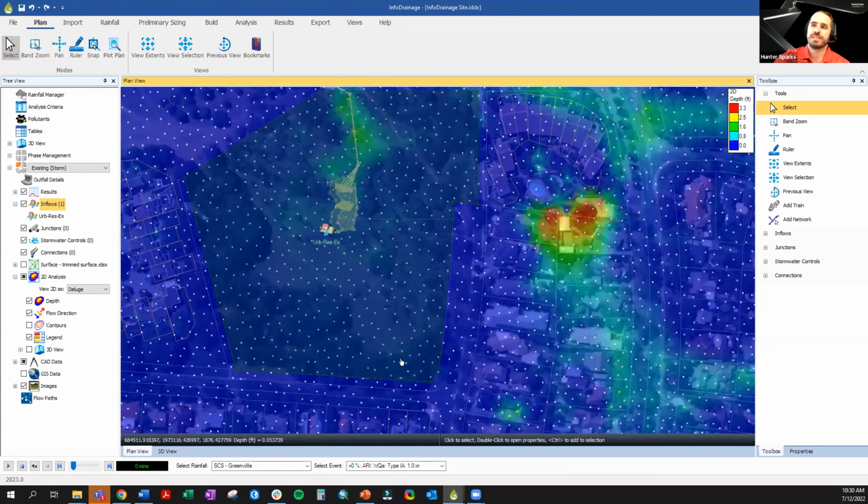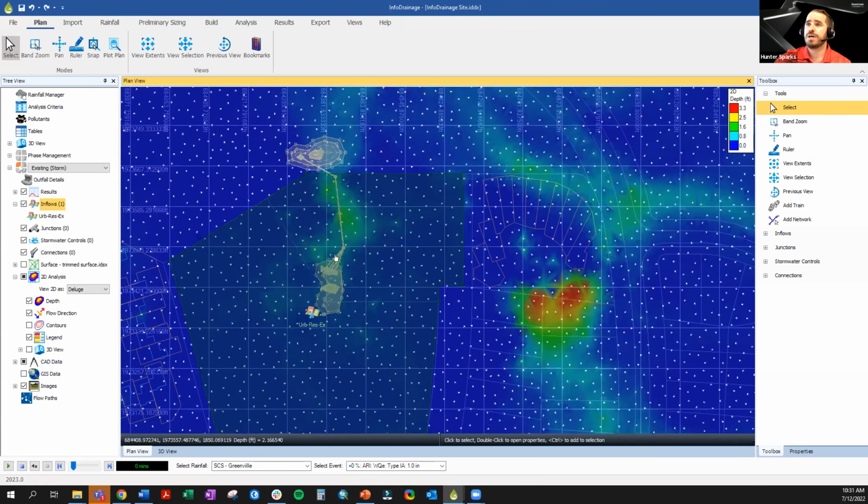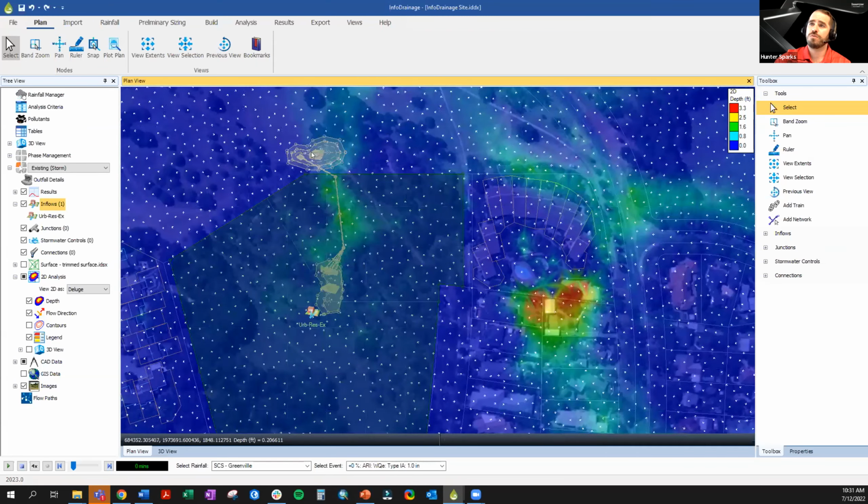But as you can see with this Deluge tool, with very simple, very easy steps, not really a ton of engineering involved, I found that I have a ridge typically running at the southern side. And as we can see, water is traditionally trying to move to the north, and you have some ponding and low points. So if you have the ability to match those low points and try to use some of that in your design, it can be more efficient, spending less money, and just kicking off your design is a lot easier and more efficient.